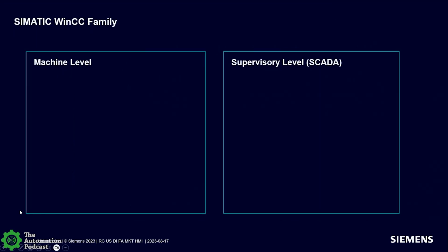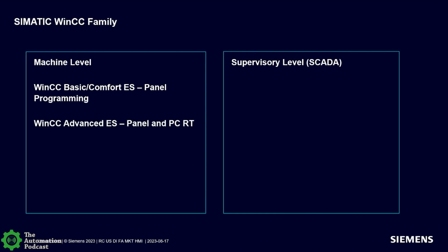WinCC is just the family name. We look at HMI software as either being a machine level application or a supervisory application. In the machine level world, at least when it comes to the software, we have WinCC Basic and Comfort as engineering software. That's the software that customers use to program our HMI panels with. We next step up to WinCC Advanced Engineering Software, which can do the panels. It's built on that, but also adds a PC-based runtime. And then we have the associated runtime software. Those are our packages that have been out since about 2010.